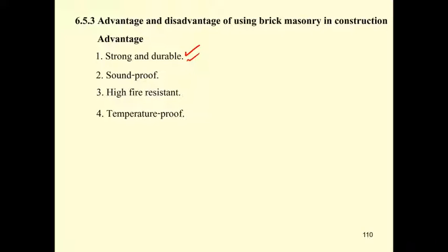So in a steel structure, you have to spray fireproofing on the steel, and in some cases, when a fire occurs in one room, the heat can transfer to another room, and if that room has some easy-to-burn material, the other room can also burn from the heat that is transferred across the steel.